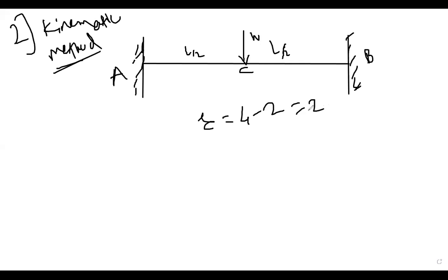That is 2. Why is it 4? Because there is no horizontal load, so we are not considering the horizontal reaction here. So vertical 2 and 2, moment 4, minus 2, equation Fy and M. So we get R is equal to 2. So number of plastic hinges is equal to how much? 3. R plus 1 is equal to 3. So where will the plastic hinges form? A, B and below the point load, correct.